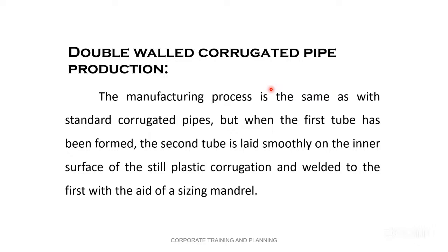Yes, sir. In screws, there are different types, like conical screw and parallel screw. They call it the twin screw method. Yes, twin screw. They are self-wiping screws. Self-wiping screws are generally used because the material should not get degraded inside the barrel. Therefore, self-wiping parallel screws are used here. Even Cincinnati screws are also used here, Cincinnati conical type of screws.